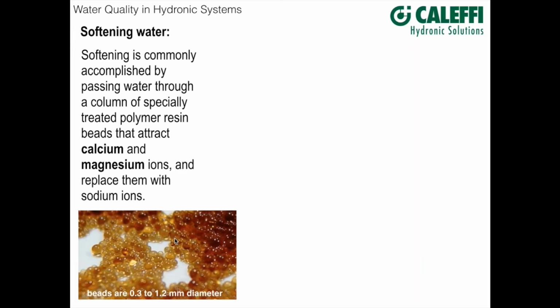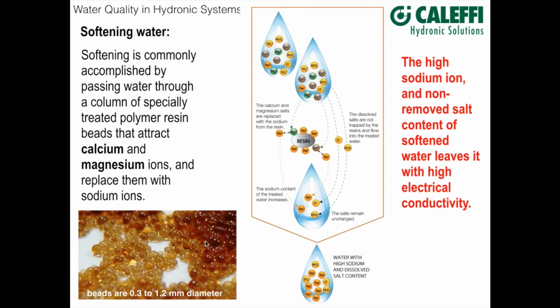They pull these ions out of solution, which is good. That's what we want to do. We want to get rid of the calcium and the magnesium. But the downside is they replace those ions with sodium ions. And this graphic here shows it.